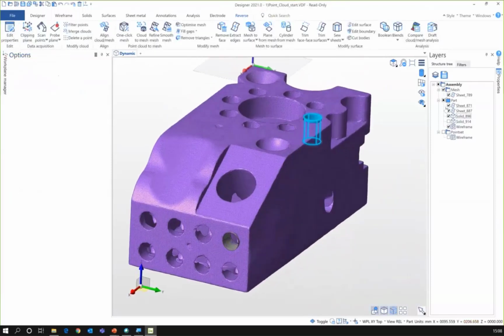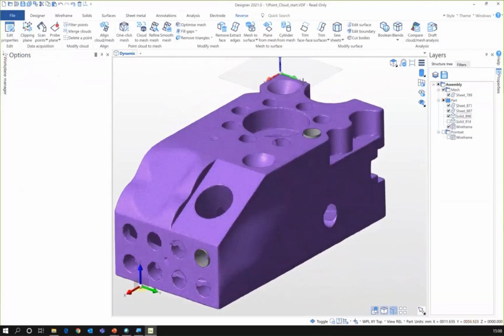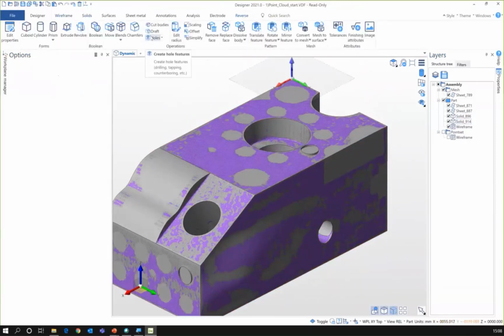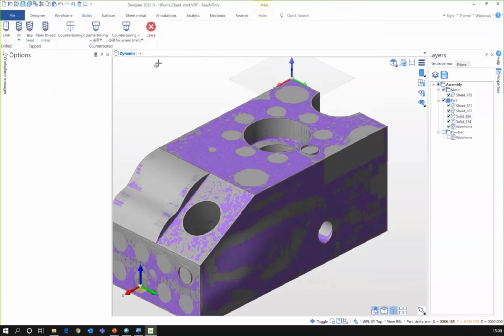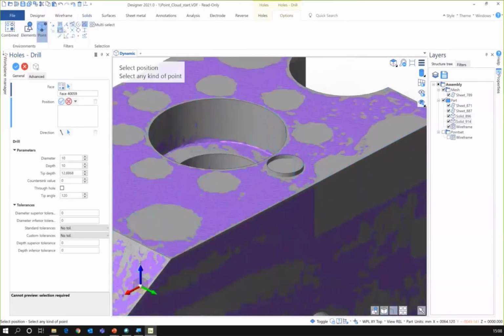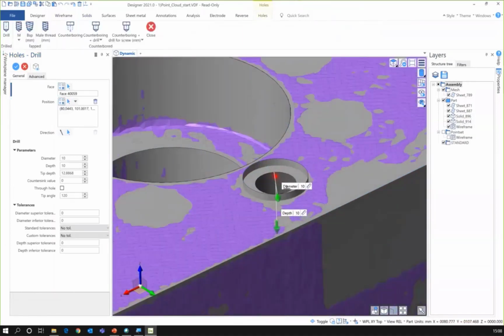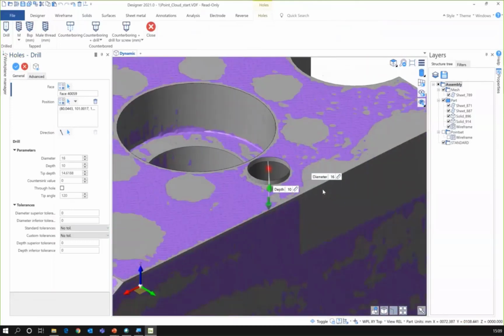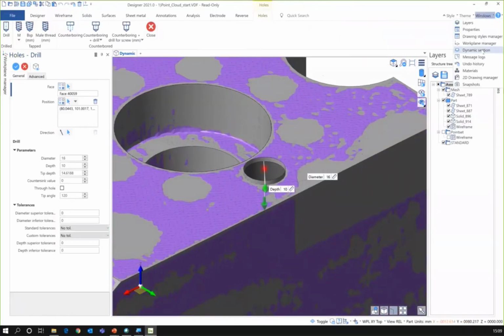All right. So if I bring back my solid, I'm going to use my hole command and create a proper drill hole rather than reverse engineering these holes and create a pattern feature. So we'll use the drill hole. I can select that face. I'm going to choose my center point picking and pick the center of that circle. We know that these guys were radius 8, so the diameter is 16. Perfect, that looks right. And now I'm going to use my dynamic section tool.